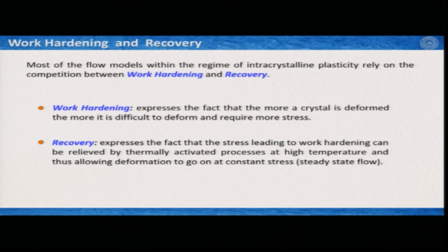So, if I start deforming it, then it requires more and more stress to continue the deformation. If I look at it in the form of a stress strain curve, after the yield it does not flow this way; you need more and more stress to deform it, and this phenomenon we learned is known as hardening or strain hardening. However, recovery is essentially the opposite process of work hardening, which expresses the fact that the stress leading to work hardening can be relieved by thermally activated processes at high temperature, thus allowing the deformation to go on at constant stress, which is also known as steady state flow.